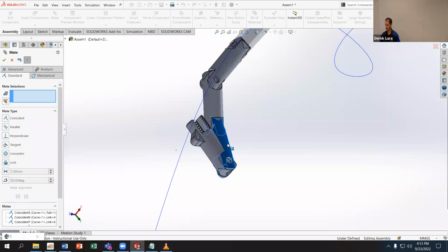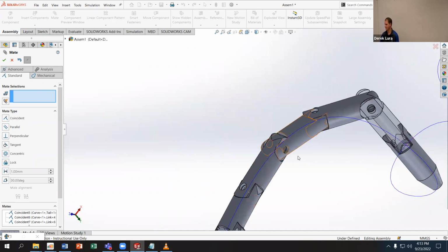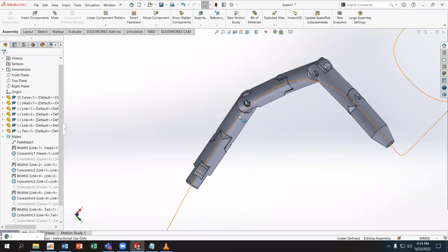And so the advantage of doing it part by part is that you can make sure that each part as it comes in is close to the correct position as you're going through. And then you don't get those situations where the configuration of the assembly is just way off and you're trying to figure out how to fix it. So it's just trying to avoid putting yourself in a situation where the geometry is not what you want it to be. Does that answer your question, Marza? Yes, thank you so much.